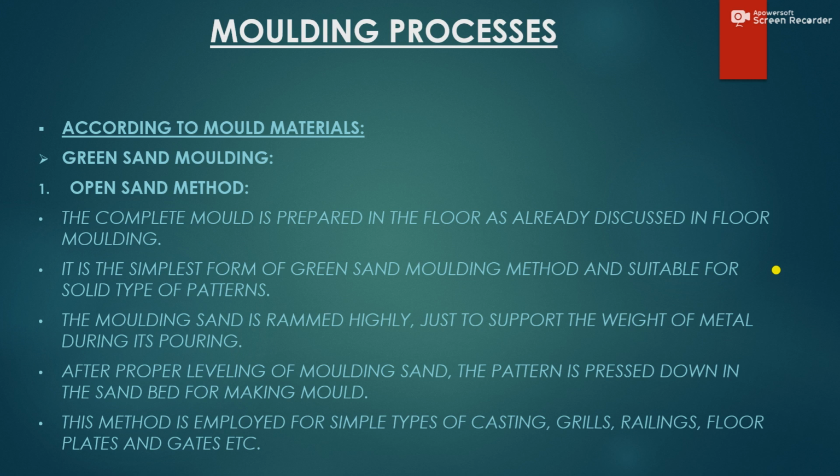So it is rammed properly, and after ramming the sand properly and leveling it, the pattern is pressed onto it, in order to prepare the mold cavity in the sand bed of the mold.